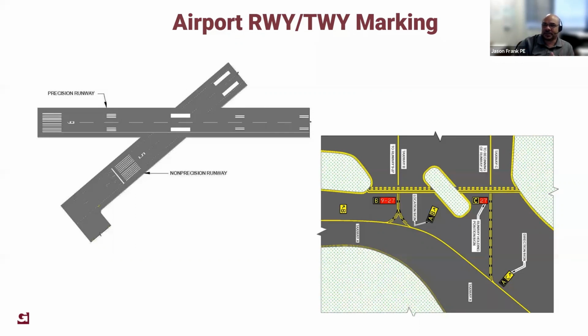So in the cockpit there, if the weather minimums are down or the weather is bad, they know that, hey, I'm coming in at 3% on this. I'm lined up with the center per the localizer telling me here on my dash, and the same with the slope. So they are identified also visually by the markings on there. A non-precision runway typically has your threshold, your landing bars, and then that's really it.